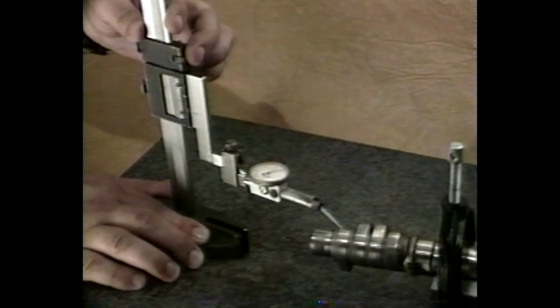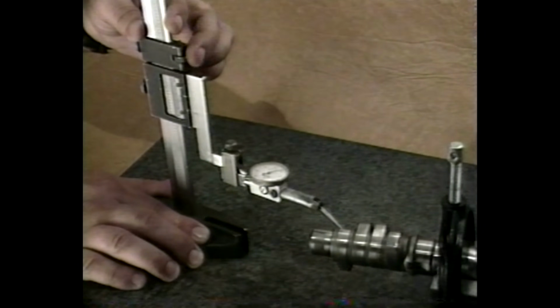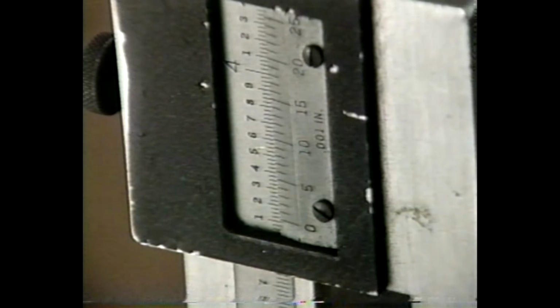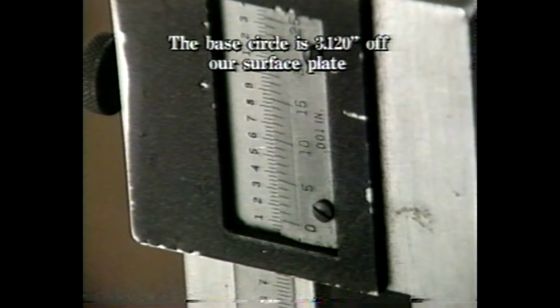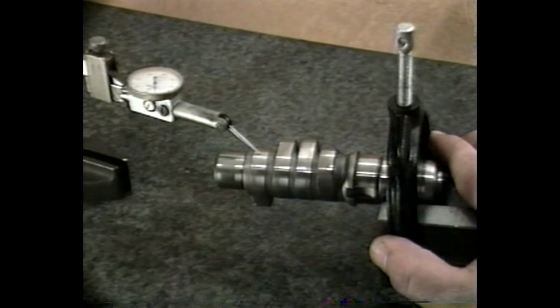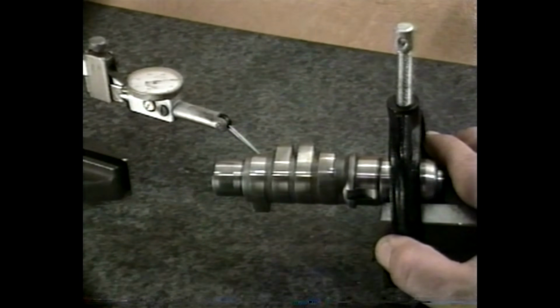With the needle of our dial indicator resting on the diameter or high point of the base circle, we continue to use the fine adjustment to slowly lower the foot of the height gauge until the dial gauge is again zeroed. Then we read the vernier scale again. The surface of the base circle is measured to be 3.120 inches off our surface plate. Note that if the needle has been bumped, or if it has changed position accidentally for any reason, we would have to start the whole procedure over again.